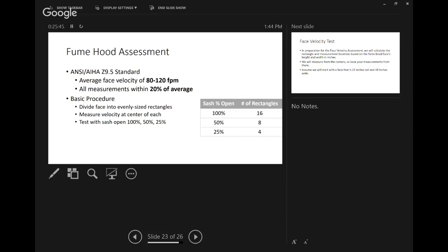And if it's too low, then like that one slide said, the table, 60 to 100 is what you want for gases and vapors to capture them. Not to transport, that's super easy, but to capture them, you need something 60 to 100.